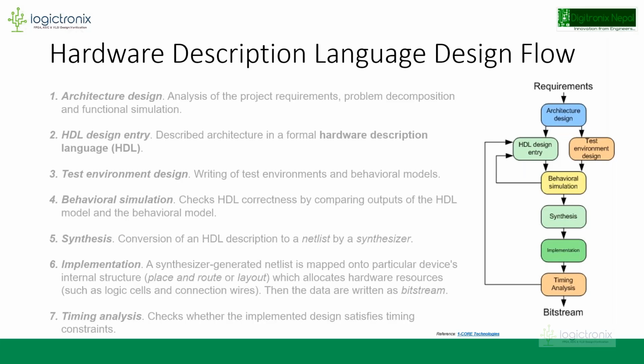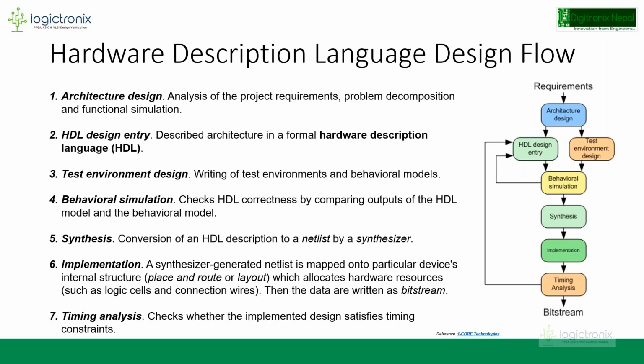In the first development of FPGAs, they were just called glue logic, because they only had a few logic gates. But nowadays the FPGA's architecture is quite changed, and it is a heterogeneous chip with lots of things inside. It consists of different logical units, different high speed interconnects, and also some processing elements like processors.